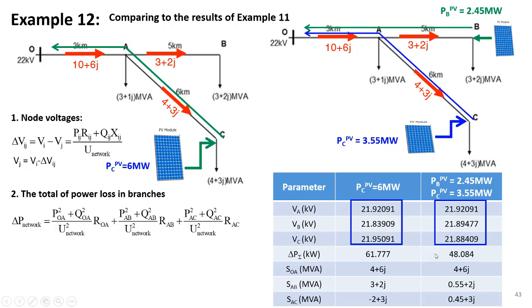More importantly, we see that the power flows in branches are reduced. Therefore, there is an opportunity for us to increase even more power at node B and node C. In other words, with the same PV power, the owner may produce more electricity and sell back more to the power supply company. We can increase load without increasing the cost for wires in the network.